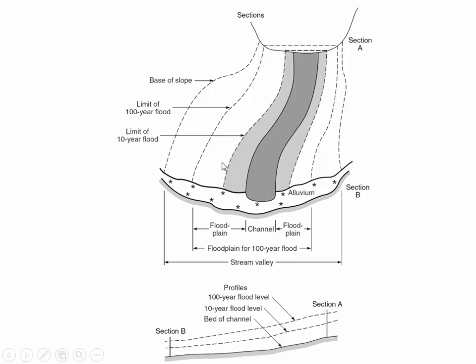And it's not just distance, how close they are to the river, but you'll notice here that the floodplain is wider than the floodplain is here. That's probably because the ground is more steep in the area where the floodplain is kind of narrow, and the ground slope is more shallow in the area where the floodplain is wide. And so maps like this are used to influence the flood classification that the government gives to properties when FEMA is calculating the risk of having flooding at a certain time.